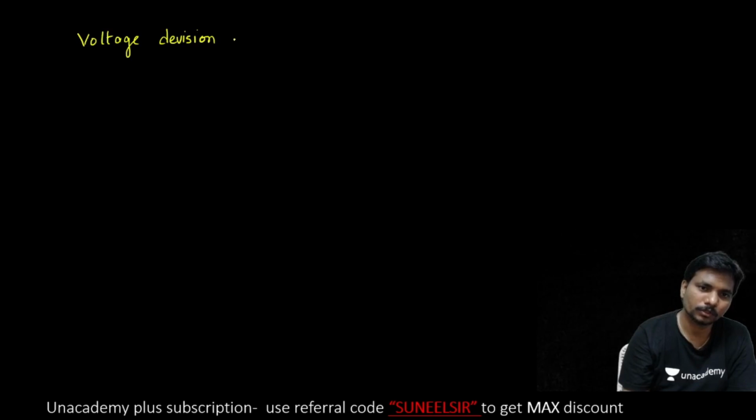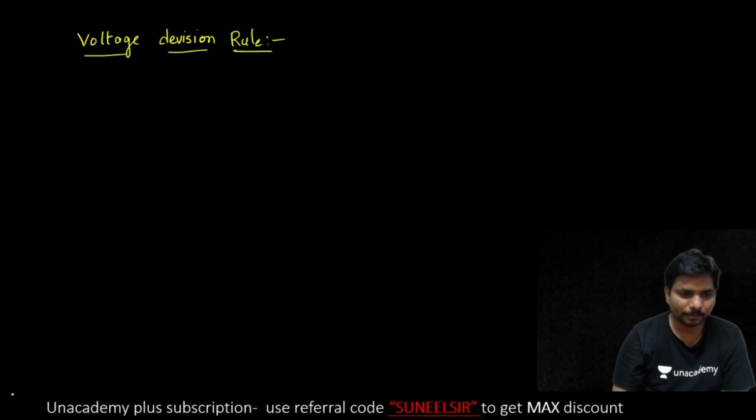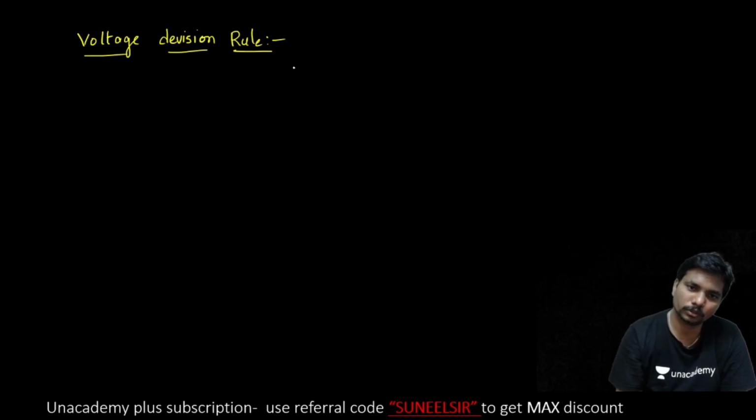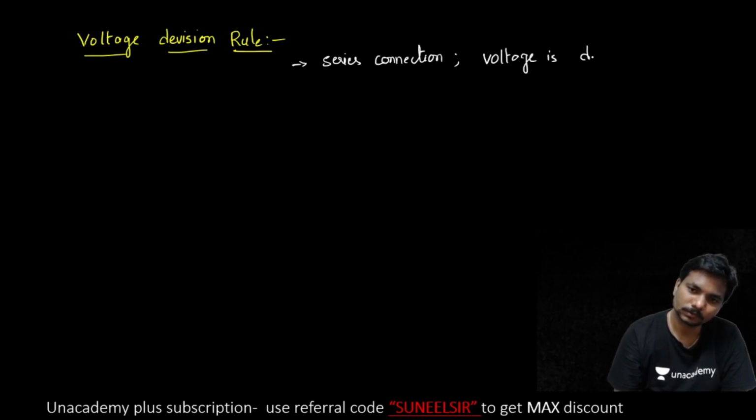Voltage division rule. You can also watch all the previous sessions by clicking on the playlist. Okay, voltage division rule. Whenever the elements are connected in series, then only this rule is useful. Why? Because in series only voltage is divided. Current is the same in the series connection. Voltage only is divided. So note down that point: series connections, voltage is divided, current is same.